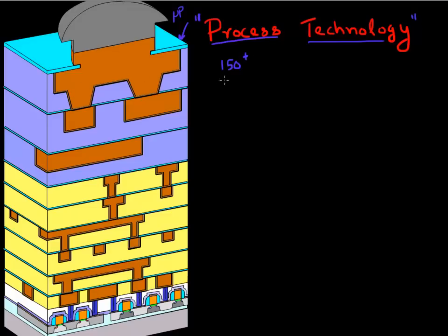And there are, as you can see, 10 plus of these layers involved in going all the way from your transistors, which are on a nanometer scale, and all the way up to your micro bumps, which you use to connect to your PCB, and these are in the micron scale. So we see that there's a three orders change in dimensions going from the transistors all the way up to the microbump, and that approximately translates into these 10 layers that you have.